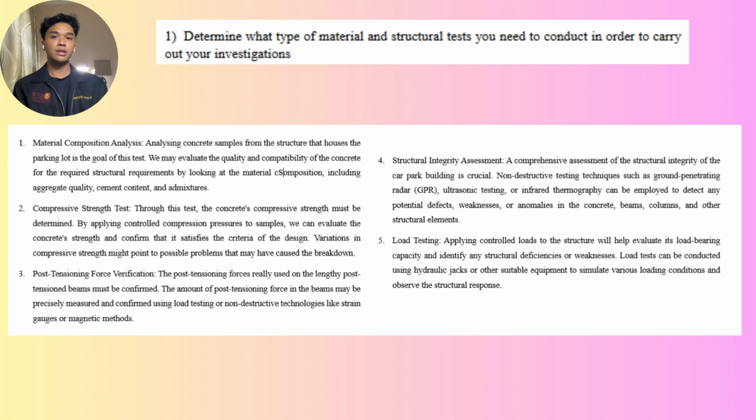testing or non-destructive techniques. The fourth one is structural integrity assessment, where we use non-destructive testing to detect defects and weaknesses in the concrete structural elements. The fifth one is load testing, where we apply controlled loads to evaluate load-bearing capacity and identify structural deficiencies. These tests will provide crucial information to understand the failure and take appropriate corrective actions.